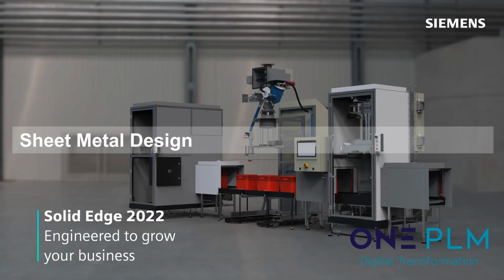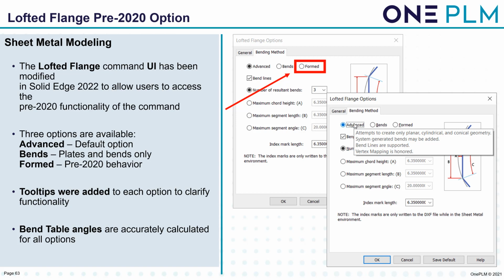So let's have a look at the changes in sheet metal design. The lofted command UI has been modified in Solid Edge 2022 to allow users to access the pre-2020 functionality of the command. Three options are available: Advanced, which is our default option; Bends, which is plates and bends only; or Formed, which is the old pre-2022 behavior. We've also added tooltips for each option to clarify the functionality that each of those is going to add. Bend table angles are accurately calculated for all options, depending on which one we choose.